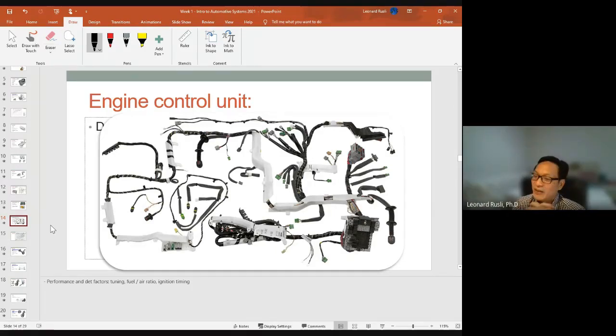Okay. These days, you don't have to. Welcome to the 20th century. They do have temperature controls. So that means when your engine is still cold, it raises the idle RPM. It also adjusts the air-fuel ratio. It adjusts the ignition timing. So it makes all kinds of adjustments that need to be made when your engine is still cold. So yeah, you don't want to drag race the car when it's cold. But other than that, you don't need to worry about it.